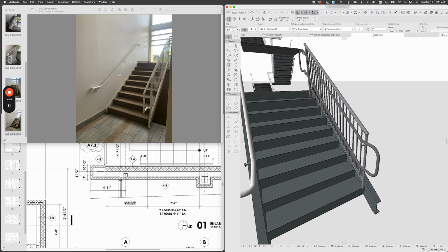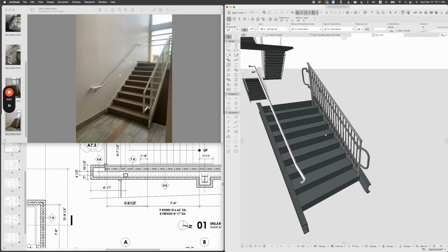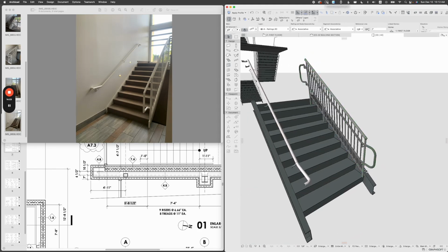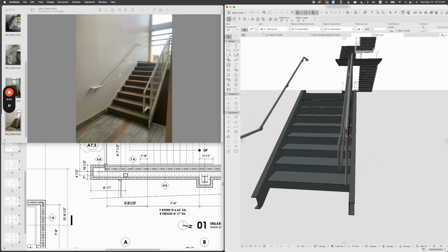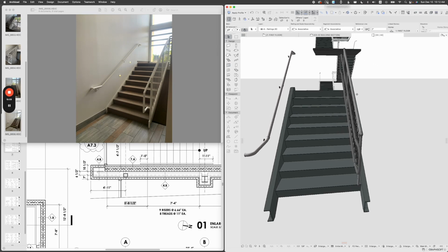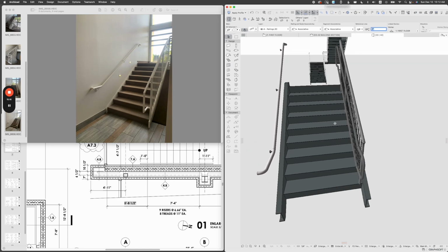Now the next step is this particular handrail. It does not sit on the stringer, and that's the problem. This is a default setting of that exact guardrail, and probably why they did this offset of 2 inches. I think because the stair could be made of concrete, and it may not have any stringers.